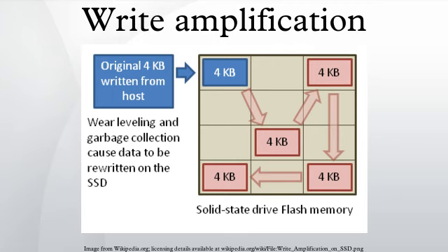If the user capacity on the SSD was 100 GB and the user actually saved 95 GB of data to the drive, any trim operation would not add more than 5 GB of free space for garbage collection and wear leveling. In those situations, increasing the amount of over-provisioning by 5 GB would allow the SSD to have more consistent performance because it would always have the additional 5 GB of free space without having to wait for the trim command to come from the OS.